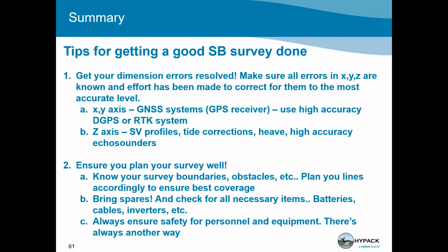Another part which I covered earlier is the Z-axis. Make sure that your SV profiles are done and your tide corrections are applied. If you need heave, make sure that your heave is applied correctly with a high precision IMU or motion sensor. These will contribute very much to the survey results that you see, so it's very important to remember these.